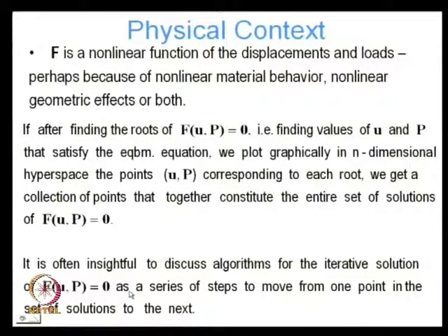Now I have all these points in that n dimensional hyperspace, and the basic problem of solving this nonlinear equation is: given a starting point, one of those infinite number of points, how do I move to the next point, and what is driving that? Well, one can drive it either by changing the displacements or by changing the loads.